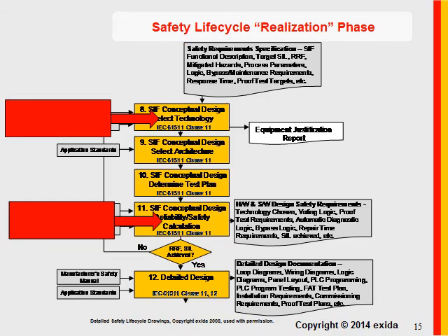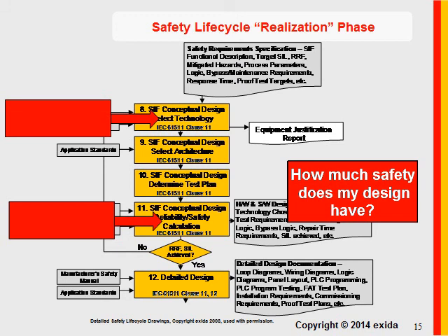When we go to the realization phase, we're trying to answer the question, how much safety does my design have? So I came up with a conceptual design, I came up with a safety function that is protecting against a certain hazard, and when I determine how much safety I have, one of the inputs is failure rate data. Failure rate data for equipment that I selected as part of my safety instrumented function. And there are also maybe technology-related aspects when it comes to failure rate data, switches versus transmitters, for example. So again, it's an input source for failure rate data.